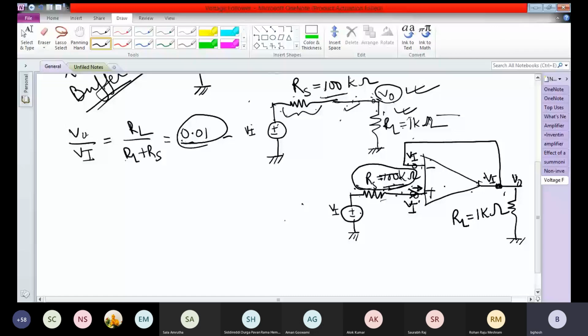So this is the job of the impedance transformer. It is because it transforms the impedance, so to say. It solves the impedance problem. So this is a very, very useful circuit component, because there will be many situations where the source resistance is not in your control, and you have to drive a particular load because this is given by the vendor to you. This is usually provided by the vendor that you have to drive this load. Such a rated current should flow through this load.